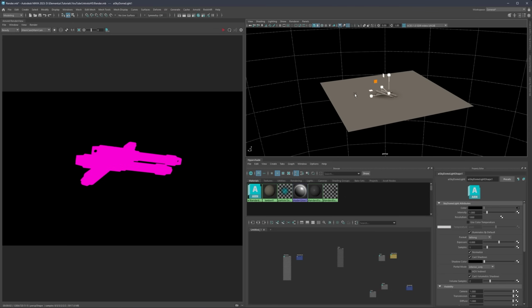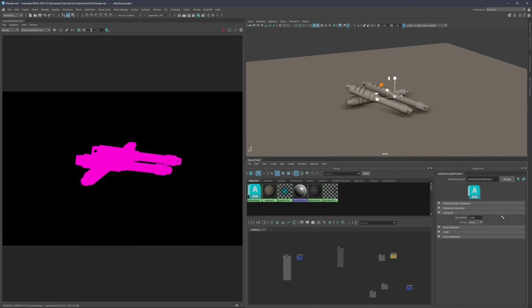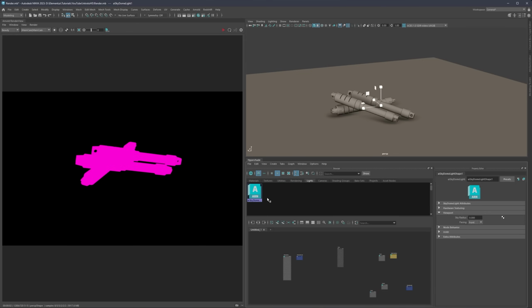So we have a skydome, we have a floor, we have a first material. Now, for example, if you would like to hide the skydome, if it's maybe too much in your way, you can go here on the viewport and simply set this value to 0. And then it's not going to be visible. Also, you can maybe set it to 10. It's going to be visible partly if you wish to edit it, something like that. But it can always be easily accessed here under lights. So you're going to have here lights, materials, probably the two tabs that you're going to use most.